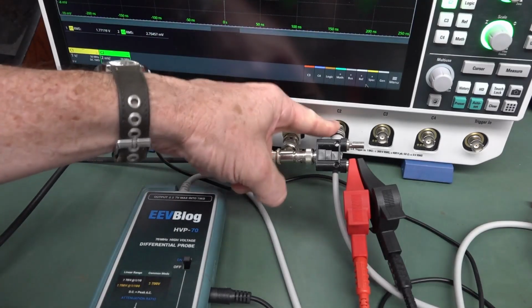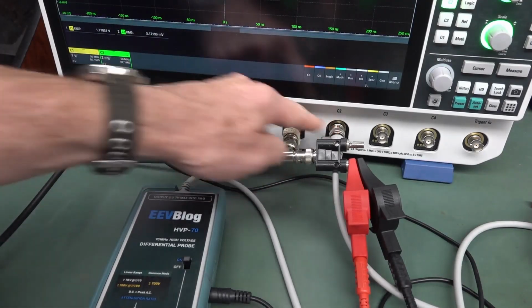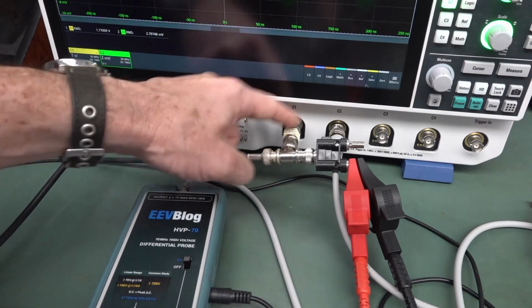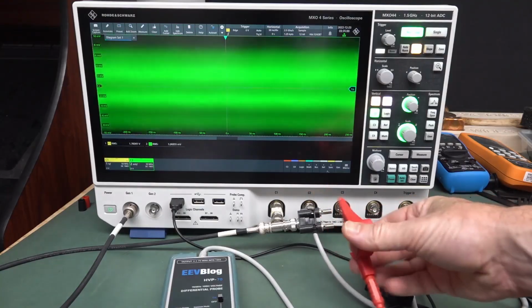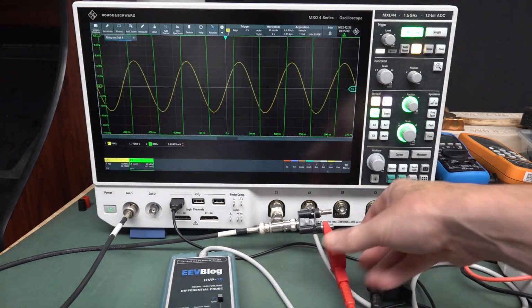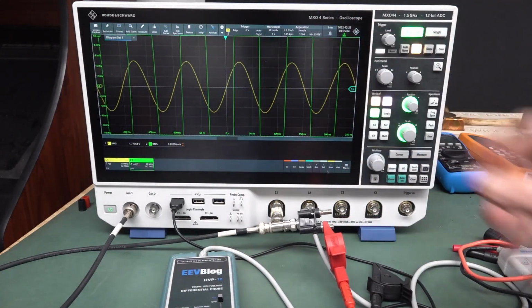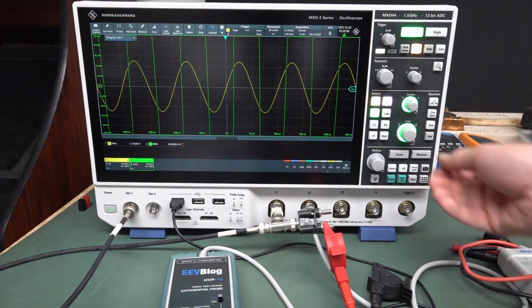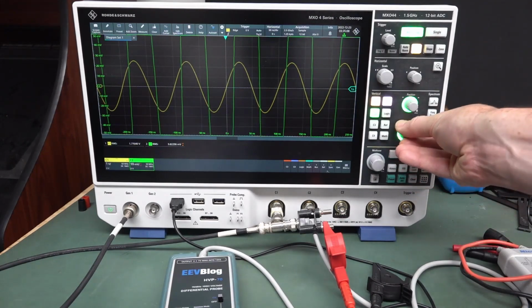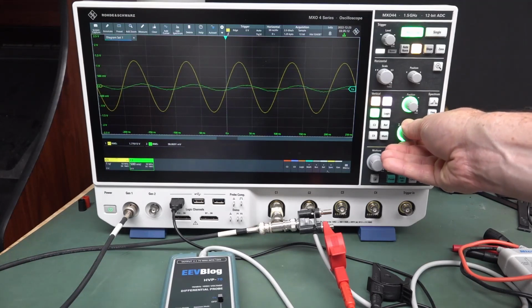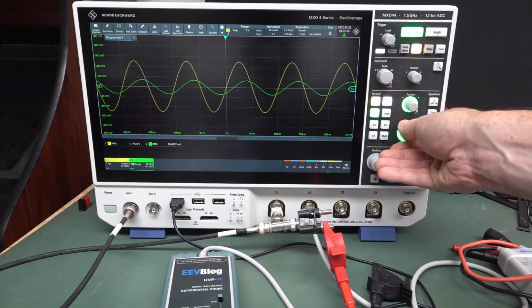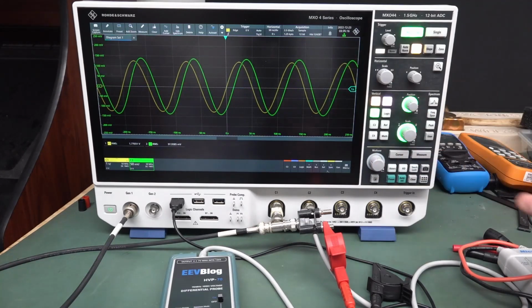Because if you remember, all the grounds on your scope are all common. So this is the input signal and the output, and they're effectively joined. They're common. So what happens if I just connect one of these to here? Well, you saw it. The green signal is the output. The yellow is our input there. And our green signal is actually going to give us an output. Here it is here. It gives us a nice, clean output like that, okay?